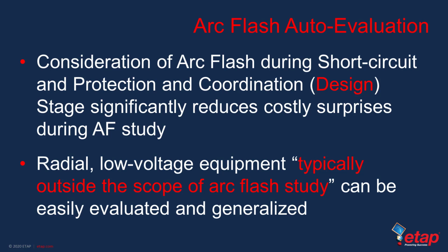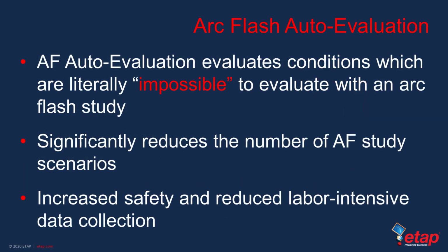Fortunately, the majority of our systems which go unanalyzed are those low current, low voltage radial feeders, and thus this tool applies to them directly. Some additional benefits besides those already mentioned are the significant reduction in the number of arc flash study scenarios and the potential reduction in the data collection for certain portions of our power system.